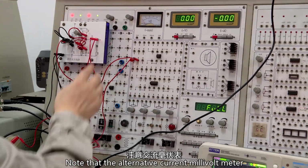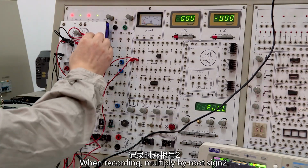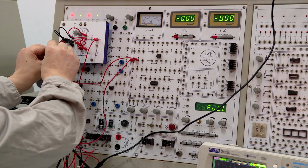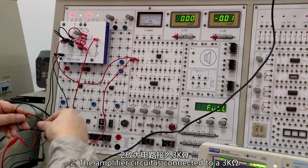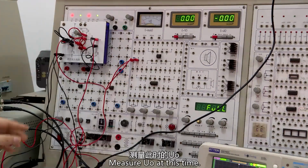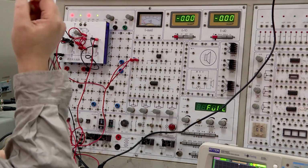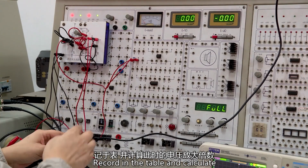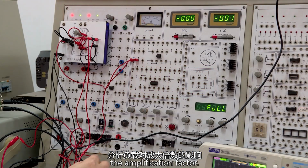Note that the alternating current millivoltmeter measures the voltage value as the RMS value. When recording, multiply by √2 and calculate according to the formula. Then connect a 3K load resistor to the amplifier circuit, connected to holes 12 and 13. Keep the input unchanged. Measure Uo at this time. Record in the table and calculate the voltage amplification factor at this time. Analyze the effect of the load on the amplification factor.